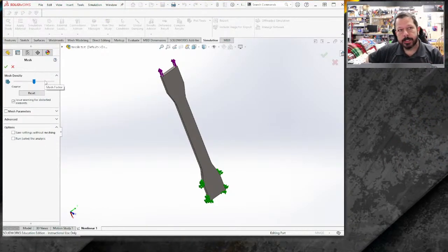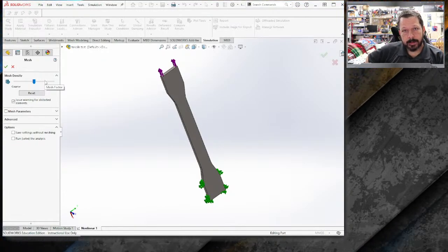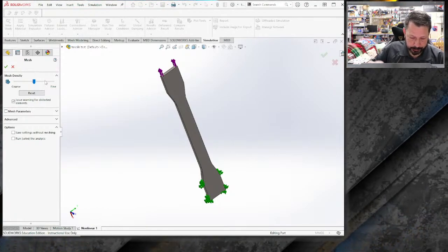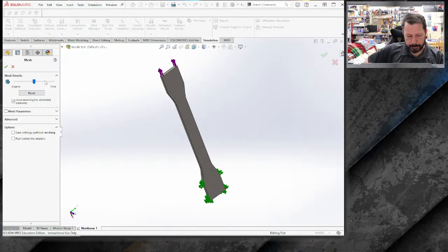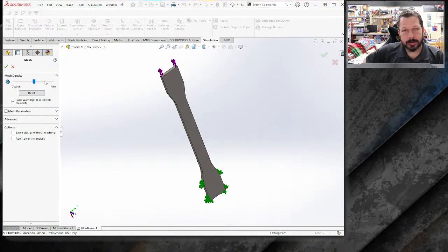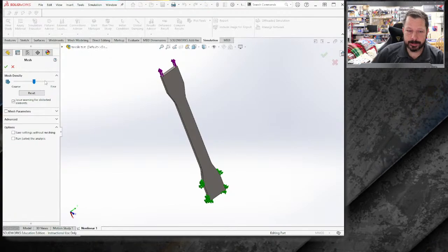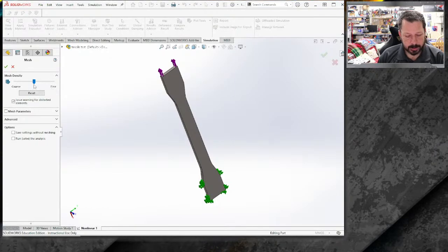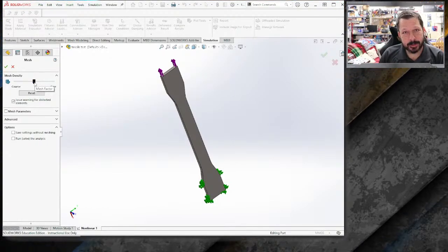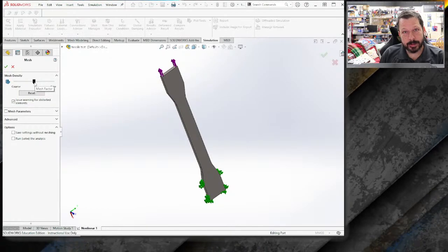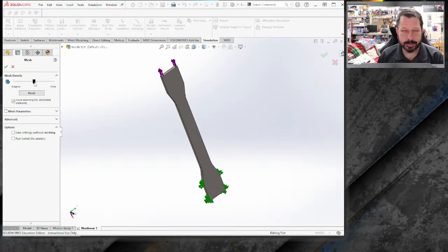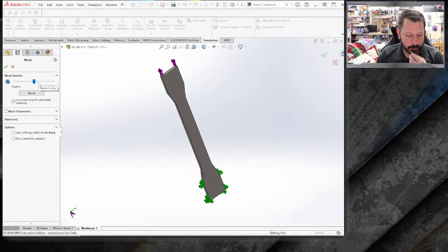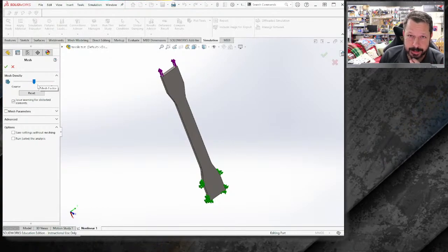Again, SolidWorks is good at letting you guide you through. It even has a wizard that will help you through all the selections you need to make. And so it makes it look like it's not all that powerful of a solver because you've just got this slider right here. Do you want more elements or fewer elements? But there's a lot behind it that you can go in and change without using these easy options I'm using. So do be aware that there's more to it than what we're doing. We're doing a first approximation type of thing today.